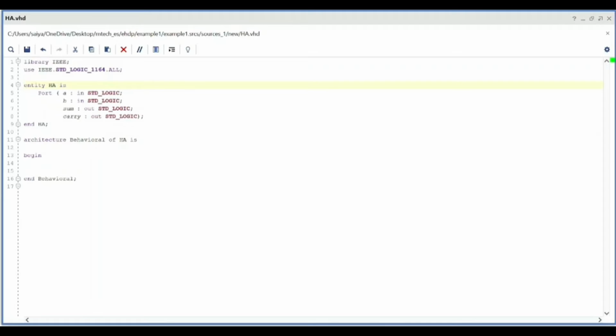Here, this is the library prerequisite I have explained. How we define it is that I will use a keyword called library to say that I am going to include a library. And what library am I including? IEEE is the library that I will be including. And any statement in VHDL should end with a semicolon.